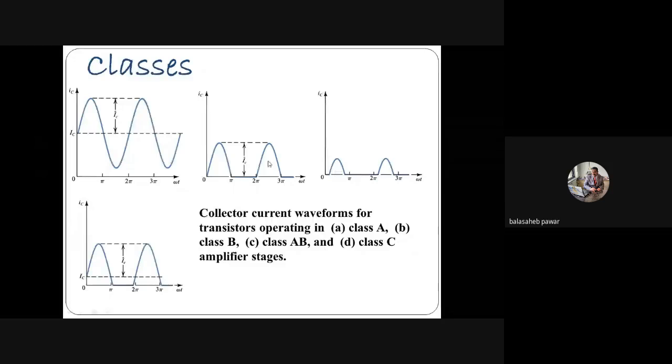See, during the positive half of input, again we are not getting that complete positive at the output. Meaning the collector current, completely during the positive half. You will observe between 0 to pi there is somewhat of a time difference, and later on we can obtain the current waveform. Is it? Again it goes to 0 before angle pi.